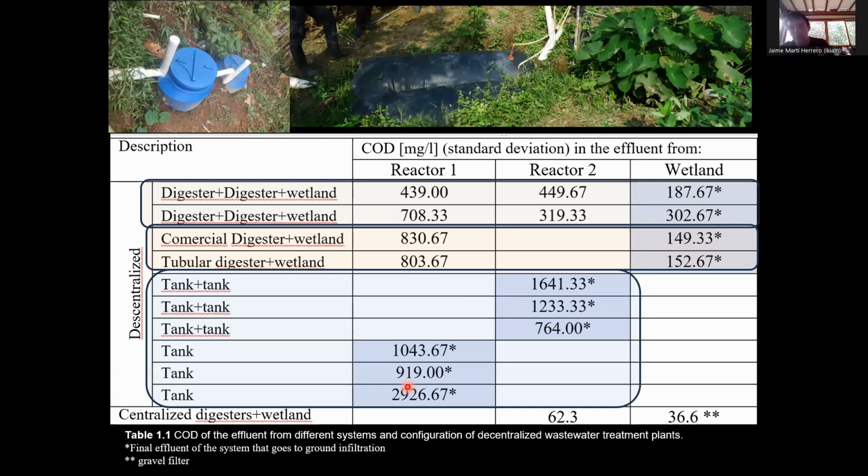But if you want to use this gas to heat the digester, you begin to complicate the system, because you will need to heat a water or a fluid, and later this fluid has to go inside the digester. You will need a pump or something to recirculate it. You need to insulate the digester in these conditions, because if you heat it, you need to keep it warm. So you begin to complicate it a lot. We never heat the digester using the biogas. The idea is, if you want to heat the digester, you can use solar radiation. That is what we did before in Bolivia.